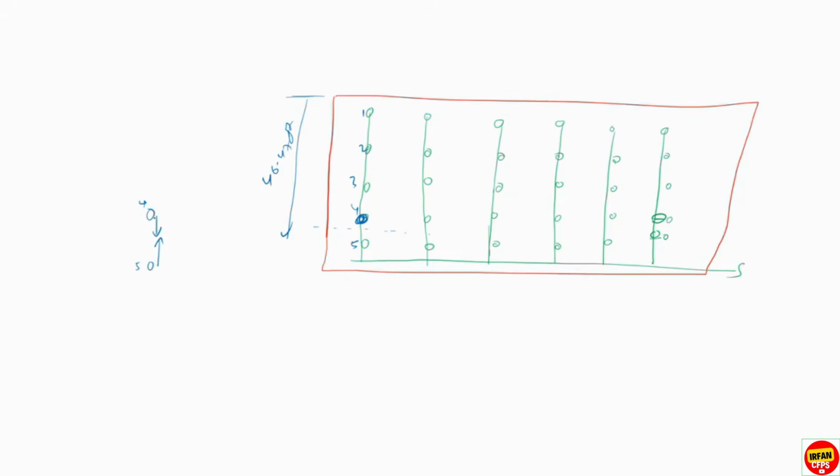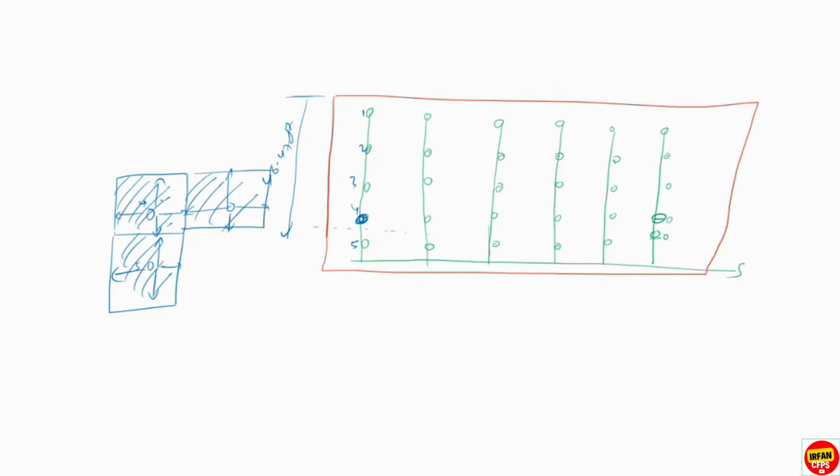And the distance, I told you, half of this coverage and half of this coverage, and half this side, half this side. Then it will be a rectangle. This is the coverage area of the sprinkler. So the coverage area will be calculated in this way: half this side, half this side. If you have one more sprinkler, half this way, half this way. So this is the coverage area. In this way you consider the coverage area of the sprinklers, half on all 4 sides.